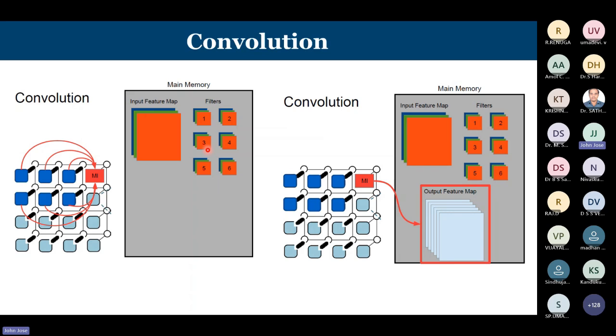So in short, if you have specialized hardware like an accelerator, what has been shown in this picture is a 16 tile accelerator. Now in this case, what we have taken is a neural network which has only 6 neurons. Since it has only 6 neurons, I'm using only the 6 blue color processing elements that have been shown. Had it been 9, then another 3 more would have been chosen. Accordingly, only the inputs and the weight values have to move.